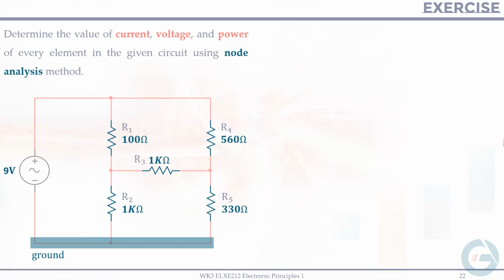So let's say we have V0, V1, V2, V4, V5. I make V3 last because if you notice, this terminal is connected to the positive of V2 and negative of V1. So you choose if this is positive or negative. The answer is either way, as long as you follow the convention in our KCL. But I will choose this terminal as positive.